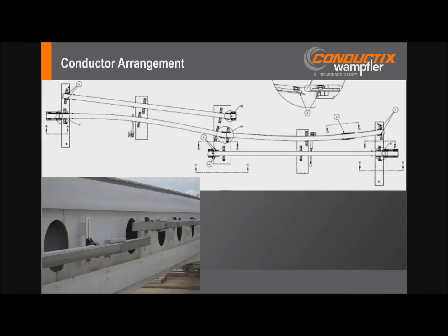For dual lane systems, it may be preferable to position the ground return conductors on the inside of the guideway, such as was done on Line 15 in Sao Paulo. This simplifies cross-bonding of the returns, but can complicate the collector configuration on the vehicles for a pinch loop system. Essentially, as the vehicle transitions through the point of crossover, you're going to have double sets of collectors as they pick up the alternated conductors.